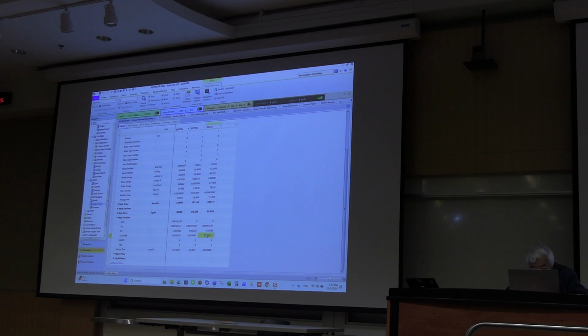Okay? Now, the key is you want to lower the mass flow rate of waste stream. While initially you have xylene at about 200 kilograms per hour, look at the mass flow. Xylene, you are losing 30 kilograms per hour to the waste stream.